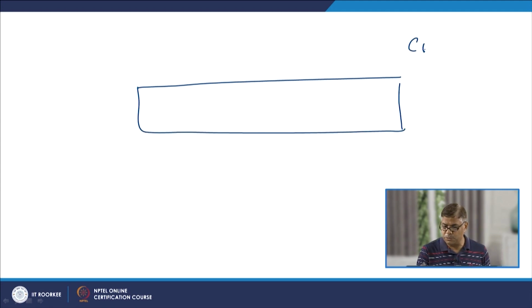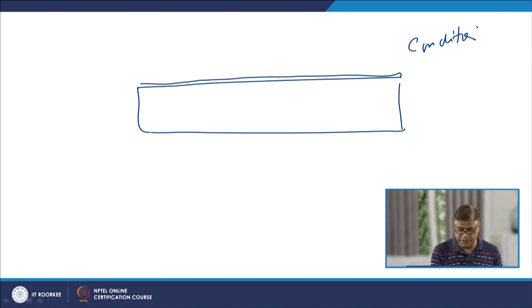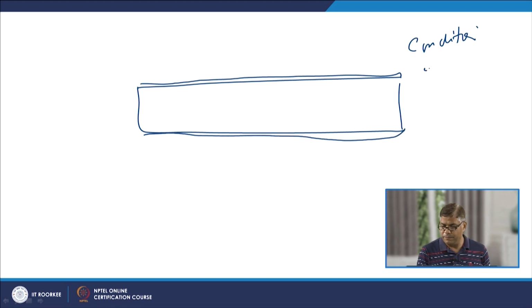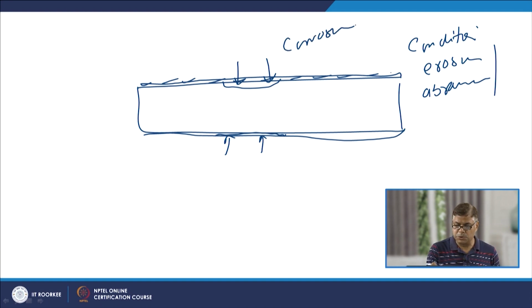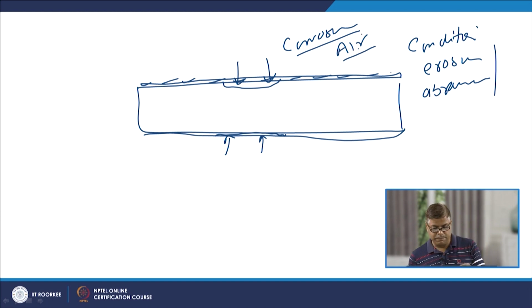If the stainless steel is exposed to conditions where this oxide layer will be damaged, like erosion or abrasion conditions, then that portion will be exposed to the surroundings, and it will be affected according to the kind of corrosive media which is present. It may be in the form of air or some specific corrosive media to which this steel is sensitive.